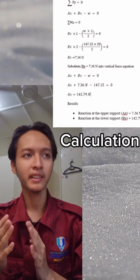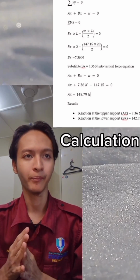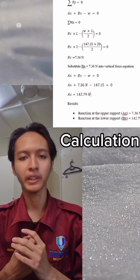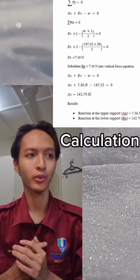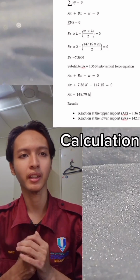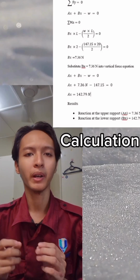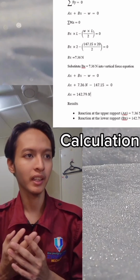Then we get Bx equal to 7.6 Newtons. After that, we substitute the Bx into the vertical force equation, the same equation that we used, which is Ax plus Bx minus weight equal to 0, and then we can get the Ax.